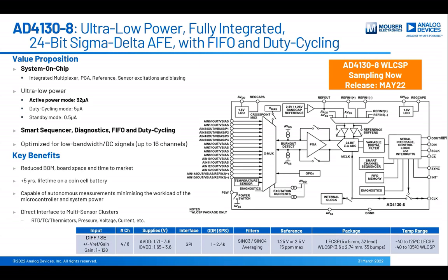It has power optimization features built in. An example of this is the sync triggered duty cycling operation. Here, the average current consumption can be brought down to as little as 5 microamps, which is really, really impressive. But we've gone even further in terms of integration functionality with a FIFO and smart sequencer on board.